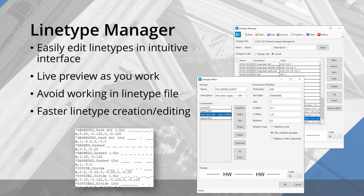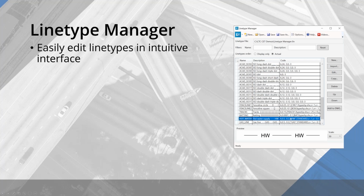One question is, does LineType Manager work with metric line types? Absolutely it does. It'll read any of those line type sizes. We're going to add a feature to this soon as well, where you can create conversions between, say, an imperial and a metric line type file. And what you'd be able to do, there'll be an option down here where you can apply a scaling factor to the dimensions or the geometric parameters in the code of that line type, and it'll easily convert between imperial and metric. So absolutely, however that line type is defined, it'll read that.